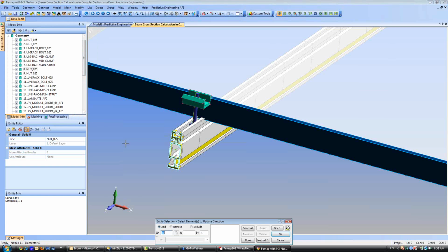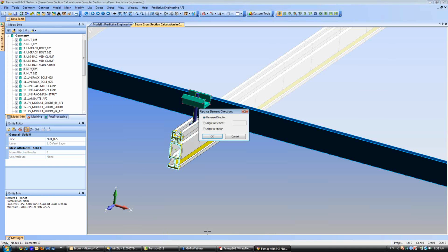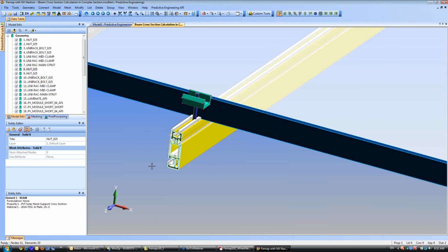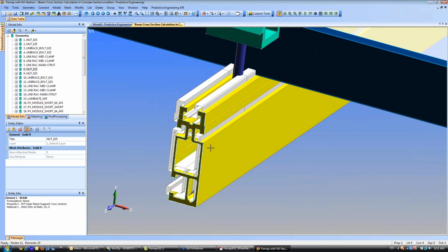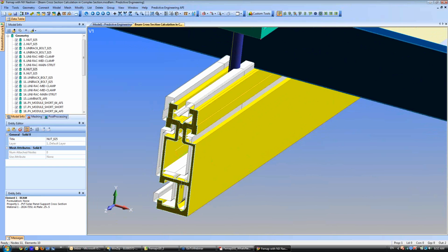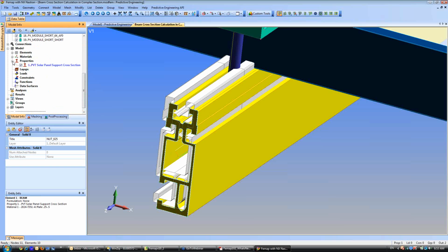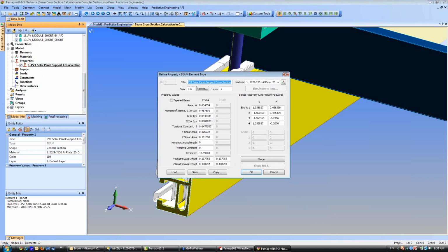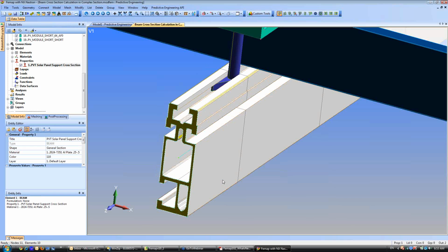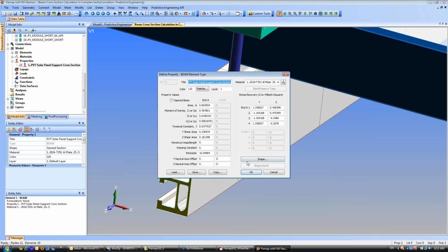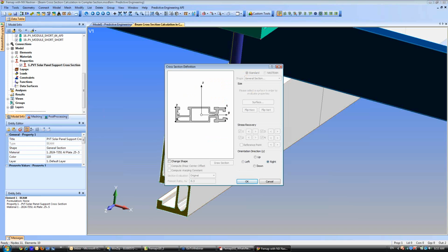This is what people find scary about beams at times. It's like, okay, there's just too much stuff to keep track of. So what I did is reverse the direction. Then you're going to say, well, what's this? It doesn't line up. This is maybe more beam theory than you want to know. That has to do with the beam offset, neutral offset. So if you get rid of that, voila, perfect.